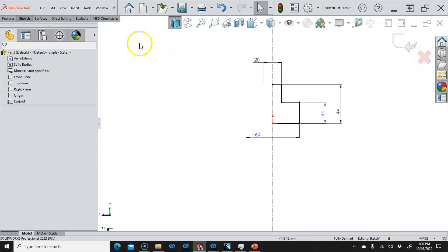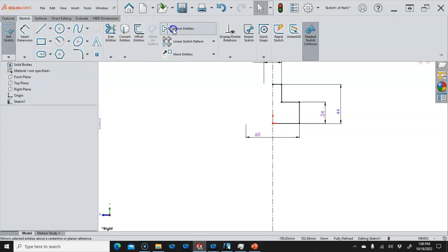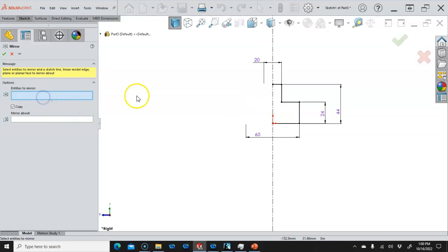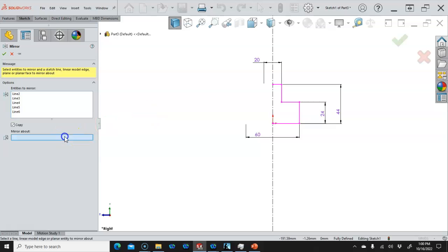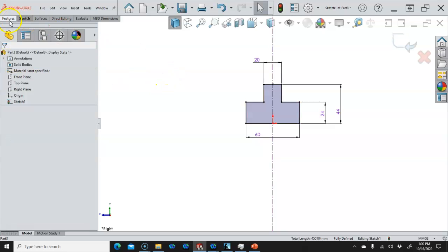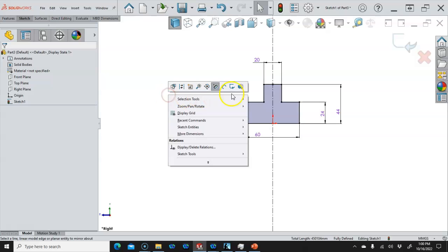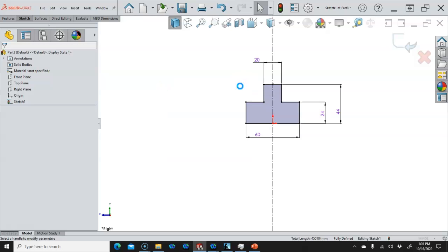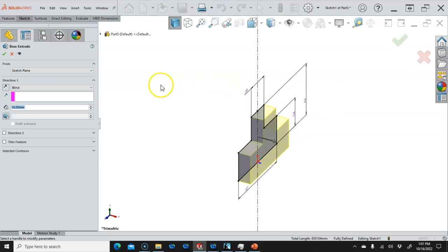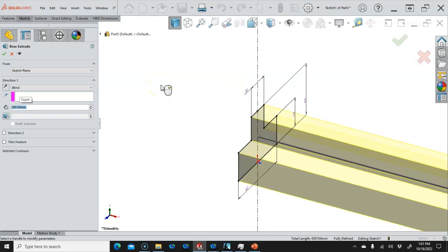If we just go into the mirror command, or go from left to right, then it will be asking us for the center line. So left to right, and pick the objects. Didn't see a preview, that was kind of weird, but still having some video issues. And once I pick the center line to mirror about, then that will generate the geometry. Let's see, for this one we can right click and extrude boss base, and the overall is 280. We'll go ahead and accept.